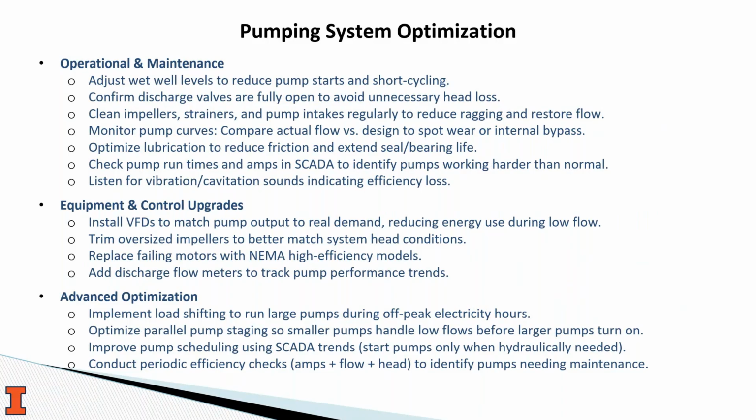You might not be seeing this issue that much, but if your discharge valves aren't fully open, or are partially closed, that can cause unnecessary head loss and force pumps to work harder. Regular maintenance like cleaning impellers, strainers, and pump intakes can also help restore flow and reduce energy use, and simply monitoring pump curves to compare flow with actual design flow can help identify whether there's some inefficiency.